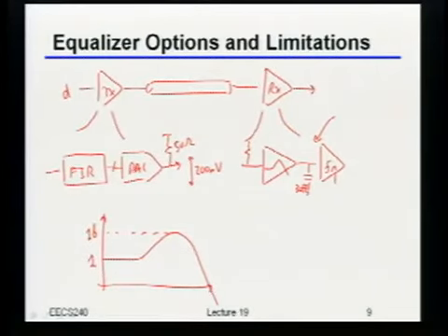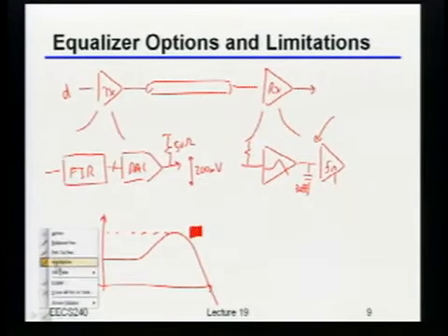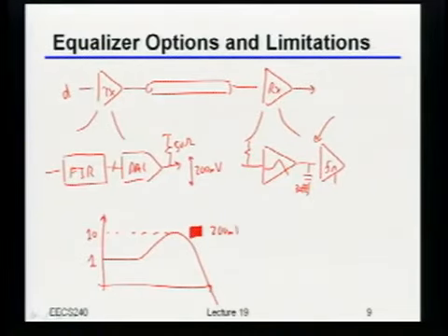So if I say that I want to transmit something with a quote-unquote gain of 10, what does that mean will be coming out of the DAC? 2 volts. Okay, well, that would have meant 2 volts, but can I actually transmit 2 volts? I can't, right? The max I can do is 200 millivolts. So what is this level going to be in millivolts? Yeah, it has to be 200 millivolts, right? Okay. What does that mean this level down here is going to be? 20 millivolts, right?